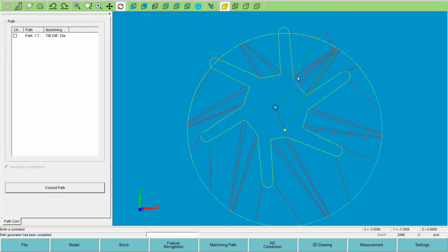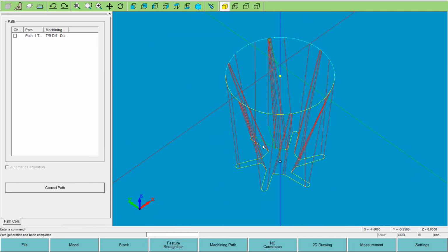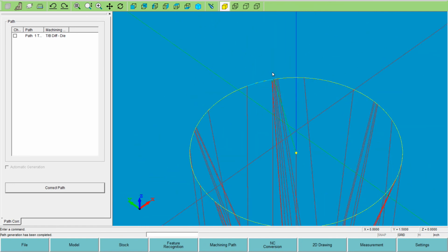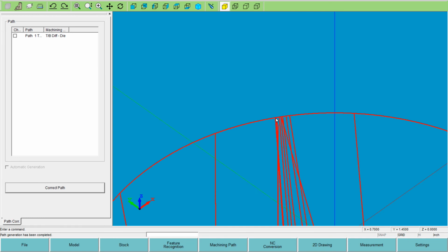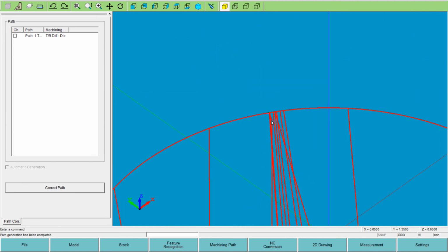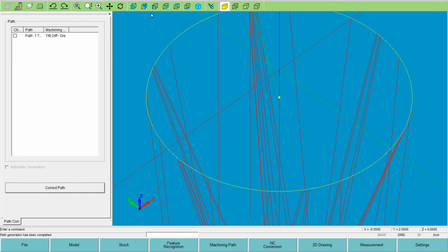So see this little move here at the bottom? Looks like it does it the wrong direction. So it released here, but the bottom cuts into the part. So that's your error message, your problem with that one. So we want to watch out. Actually, if you're doing one part, it'll be okay. You can just make the code, and I'm pretty sure what's going to show you, the machine just stops here and then it keeps going. It doesn't do this little move. It actually keeps going, and then it goes back to zeros or your start hole. It doesn't actually do this move, but if you're doing multi, it will. So I'm just explaining this, so in case you use multi, you got to watch for this.